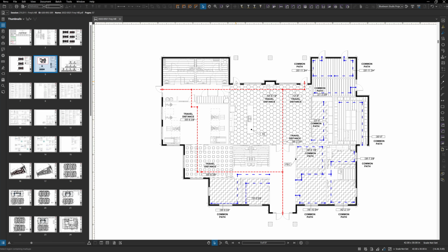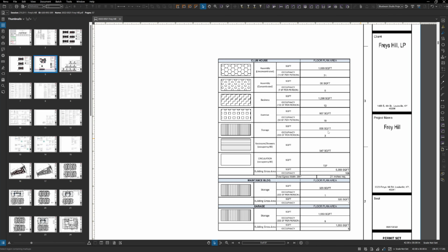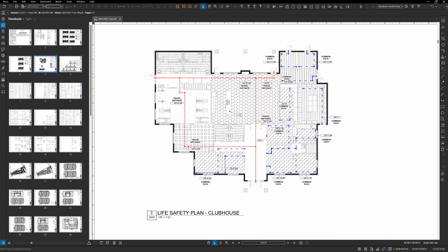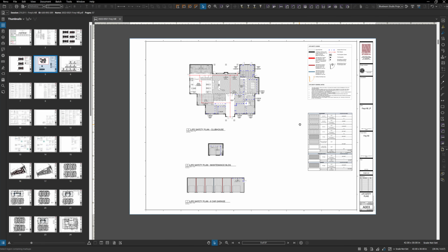Minor things, I would have shown that this also is an egress door. But other than that, it looks pretty good. Again, tabulating just a little bit of math, total egress width, you're good to go. Sometimes on these clubhouses, the only thing I see, there are certain jurisdictions that want us to rate the mechanical room as a 1 hour wall, and then always if there's a laundry room, they want us to rate the laundry room sometimes as a fire partition, sometimes as a fire barrier.